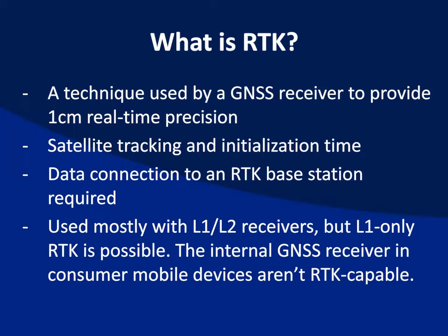But even in metro areas, you find dead spots, and it's of course more challenging out in rural areas, especially when you think about RTK users in farming. That's why a lot of them still use 900 megahertz radios or even UHF. But anyway, the point there is that if you don't have that data connection, then you're going to be super frustrated with RTK, because you've got to have a solid internet connection or data communication in general.